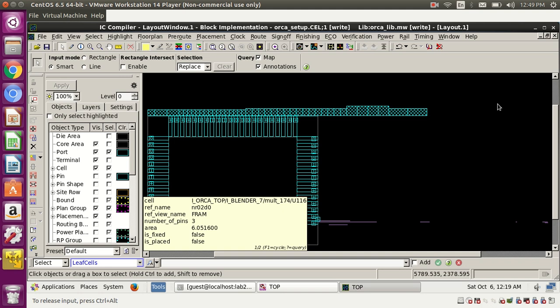So whatever is next to that has to be even bigger. If the standard cell is giving the power and M1 is taking it, M2 will not take it. So M2 should definitely be wider so that it can travel. When it is coming from M2 to M1 it's okay even if it is less, because it is going to the standard cell itself. I think you got my point.